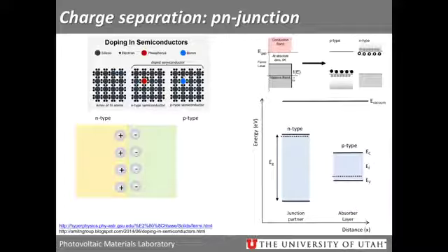So where you've added extra free carrier holes and electrons before diffusion, after diffusion, you leave those atoms behind that are in a charged state. So does that make sense? So where you have phosphorus with an extra electron, that electron diffuses away, and all of a sudden you have phosphorus with a positive charge on it, and that is fixed. So you have a built-in electric field there.